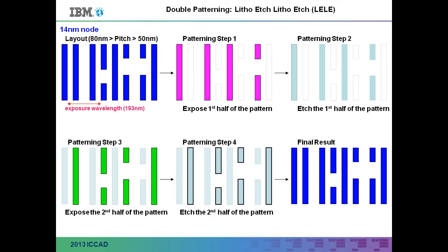Now, why 50 nanometers? I have no really hard scientific number for why it's not 40. You can do 80 nanometers in a single expose. You do that twice, you should be able to get to 40 nanometers. The somewhat hand-waving argument is that we become constrained by overlay rather than diffraction limited resolution.